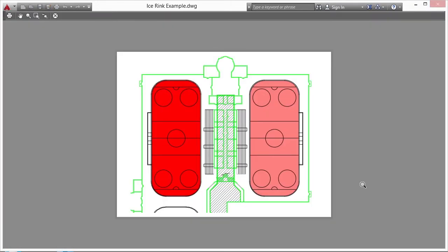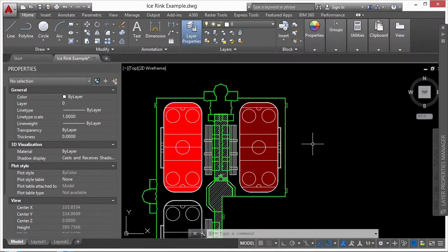So if I look at the preview, you can see this line work is faded back quite a bit. So there's a big difference. So the transparency setting works great if you have a lot of different hatches you have to do, but they're very solid and it covers up a lot of their line work. You may want to fade that back a little bit. I suggest you start off by looking between 40, 50, and 60% of your fading for your transparency. And go from there and see what works best in that specific situation.